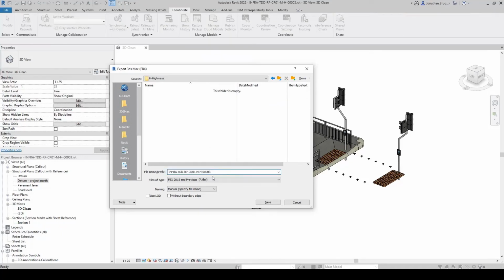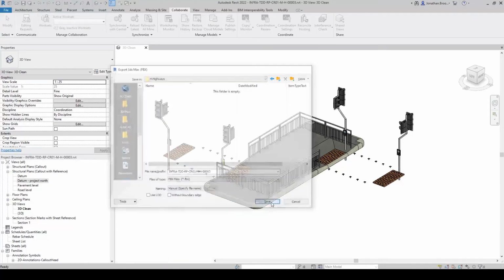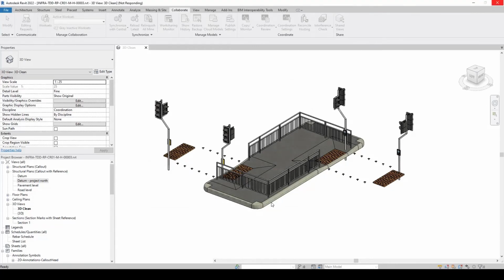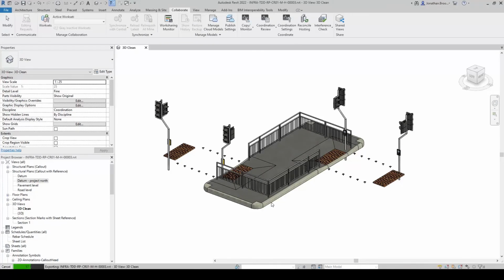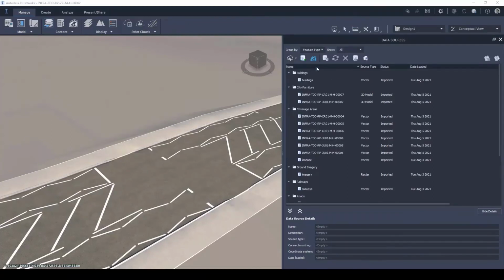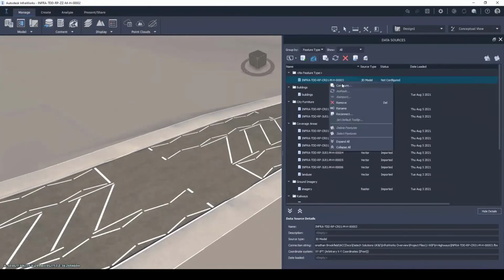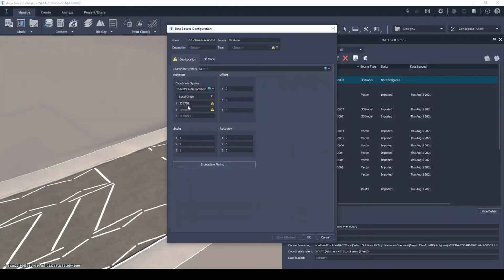If we import a Revit model, it is live linked and can be easily updated as and when it is progressed. It also mitigates the need for further files to be created. Alternatively, the FBX file is frozen in time but is more lightweight, aiding in navigational performance, and better aesthetically, as the Revit materials will be exported as is. The model can be geographically referenced, taking into consideration the project base point and rotational spatial data.